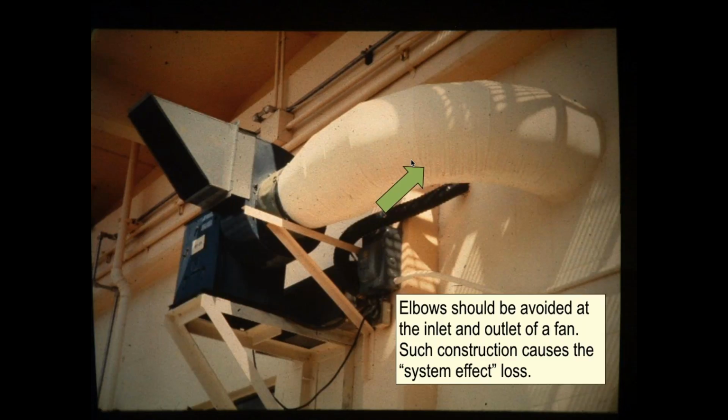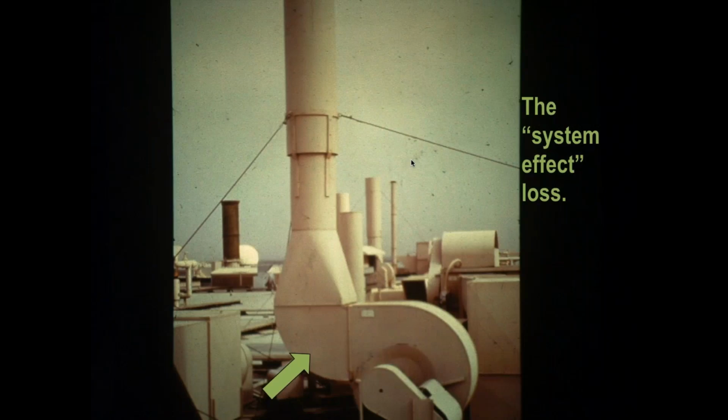If you keep that 6 times the diameter before and 3 times the diameter after, before you make any turns. Right? What's that? The diameter of the duct. Yes, the diameter of the duct. Yep. We actually have some samples of this as we get there.